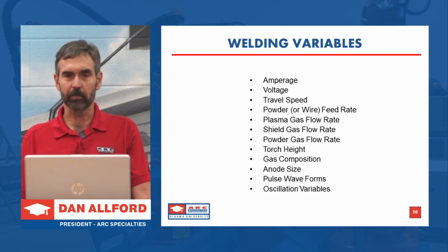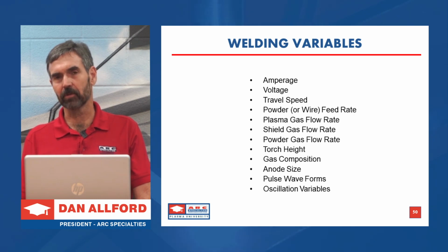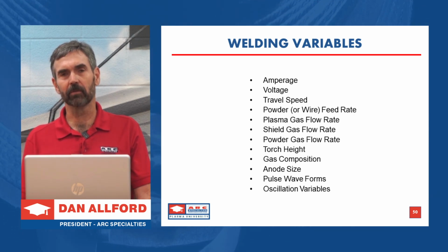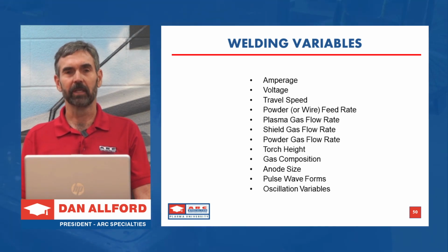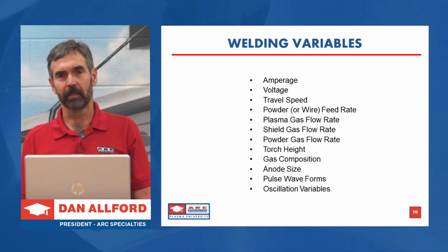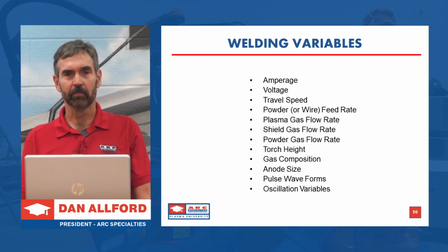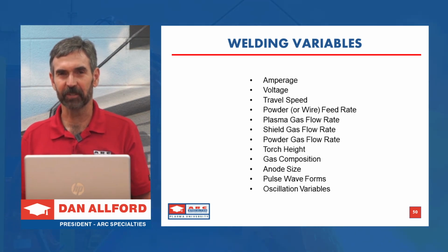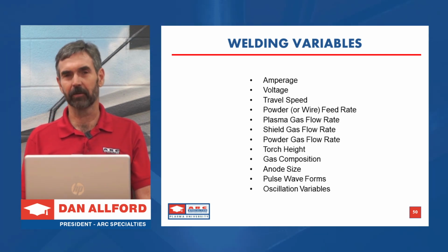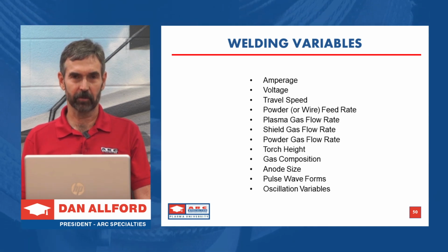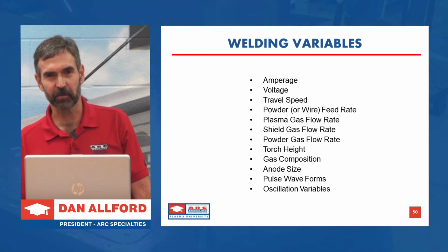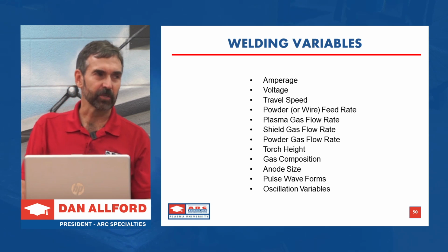And then waveforms. You saw on most of the videos I showed earlier, we're actually pulsing the arc. So you can get a lower overall heat input if you pulse high and low, and the average is actually less than what you would need if you ran a constant state. But now you've introduced 4 more variables. You have pulse peak, pulse background, peak duration, and background duration. That's if you're using a standard square wave, and it can get worse. We're going to show you some of that.